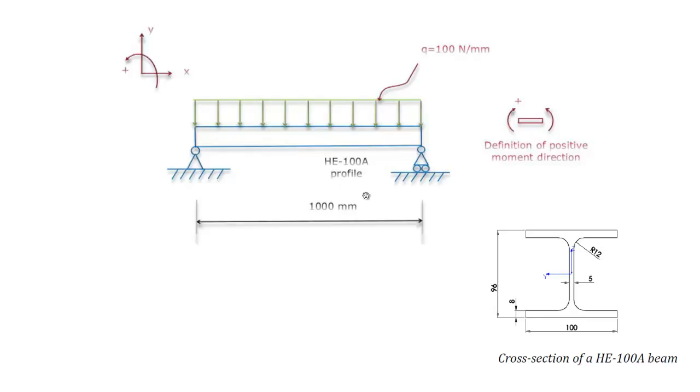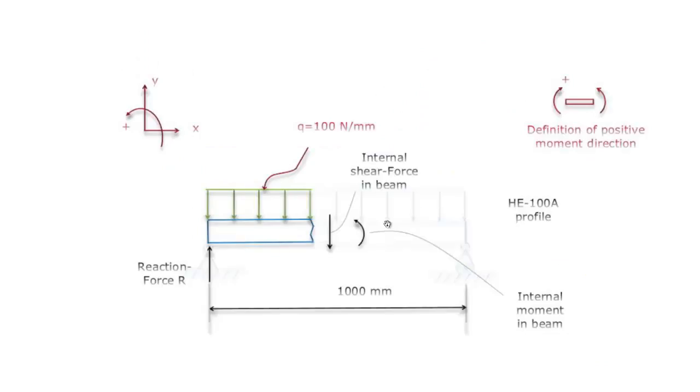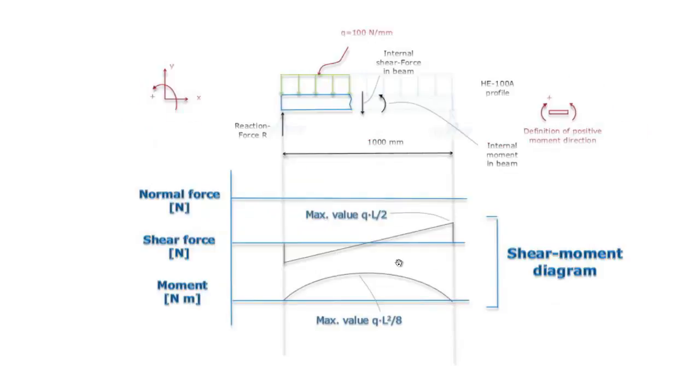It's called Autodesk Forceeffect. It won't give you all the results that commercial FEM packages will give you, but it can give you a lot of helpful results already. So here you have the drawing of the beam with a virtual cut. The beam has been cut here in the middle to get the value of the internal moment in the beam, and I've already done this calculation with the shear and moment diagrams over here.